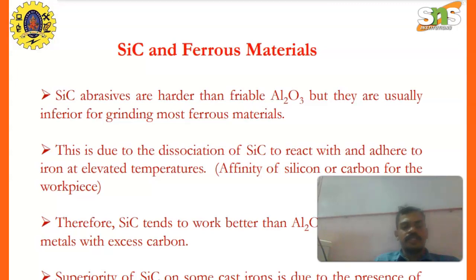This is due to the dissociation of SiC to react with the adhering iron at elevated temperature, and the affinity of silicon or carbon for the workpiece.